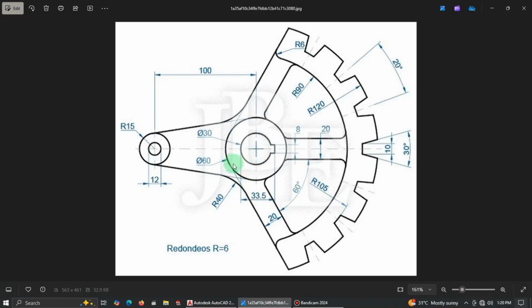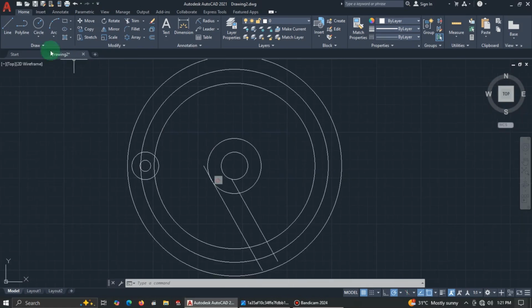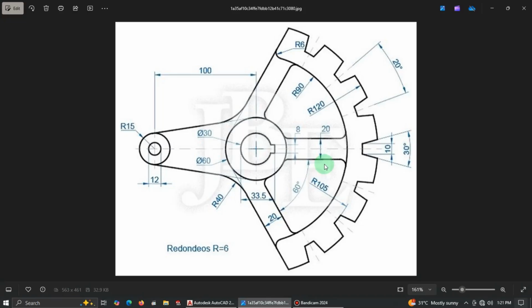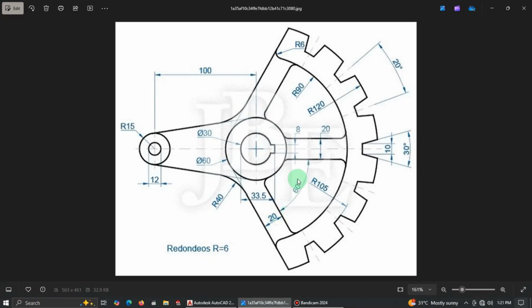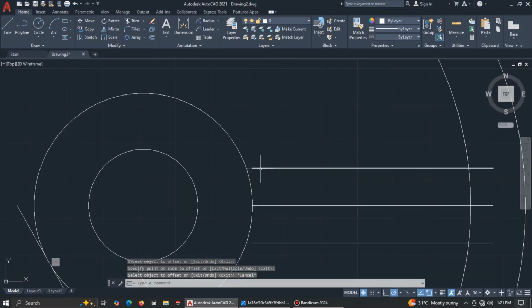Alright, so we are going to draw a straight line from this place, also 20. Okay, so let's pick a line, and from the center here to, let's make it here, offset, enter distance of 10, up and down. Good. Now let's try and see, there are some fillets over here, so let's apply them. So you can just drag this one to meet.